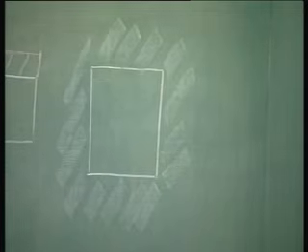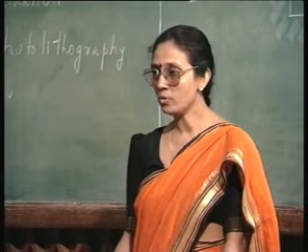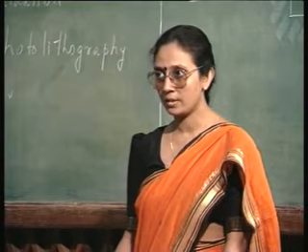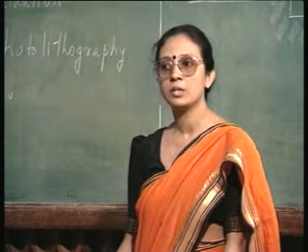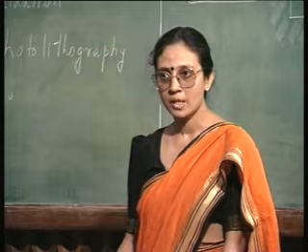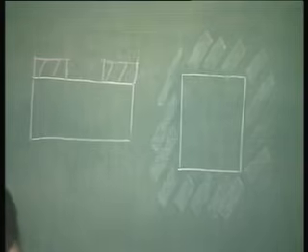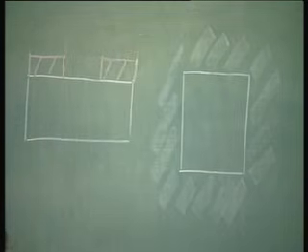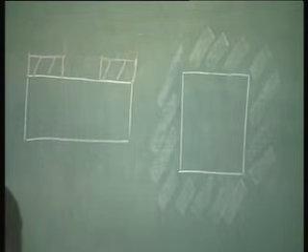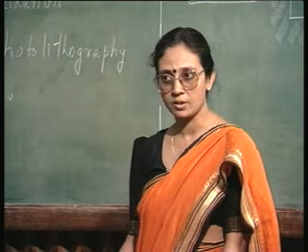One transparent square box, that is the top view of the mask plate. The rest of the portion is all dark. So, only through this transparent square the photoresist is exposed to the UV radiation, it gets softened and easy to remove, so that you can etch the underlying oxide when you put it in hydrofluoric acid solution.